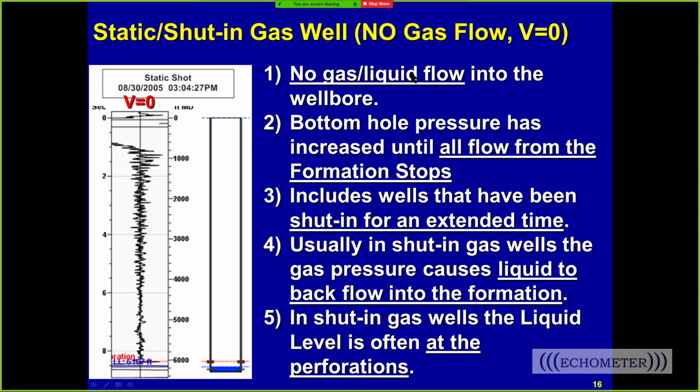So in this well, there was no gas flowing in and no liquid flowing in the wellbore. The increasing gas pressure had stopped it and equalized at the bottom of the well, and the pressure stopped changing at the surface. It had been shut in for 6 weeks. It doesn't always take that long, and that tends to push all the liquid back out into the formation, the fractures, and the perforations, and this is what you'd expect.